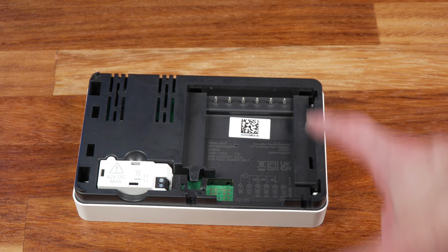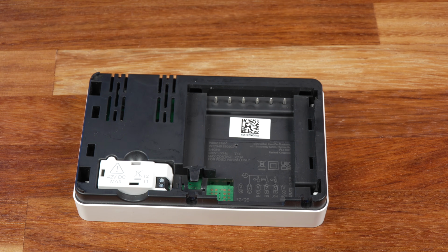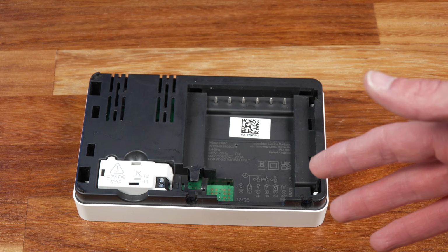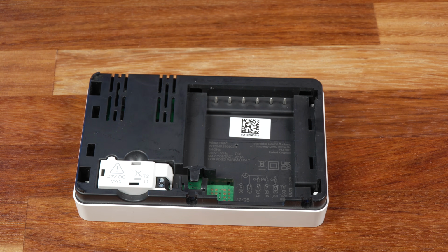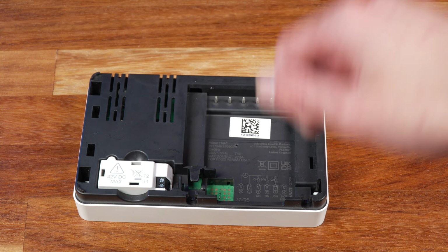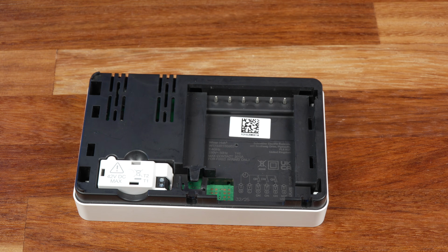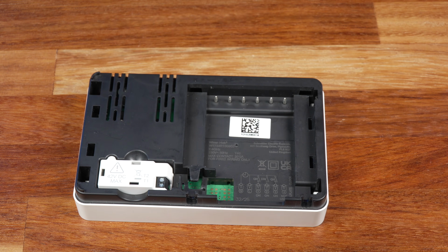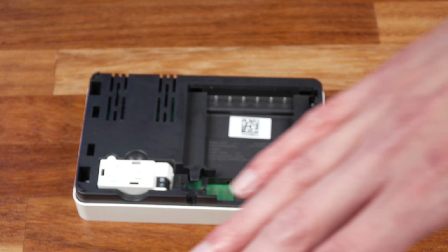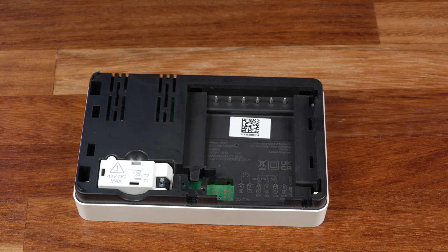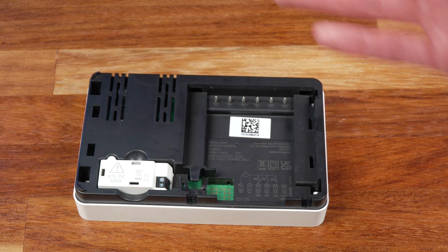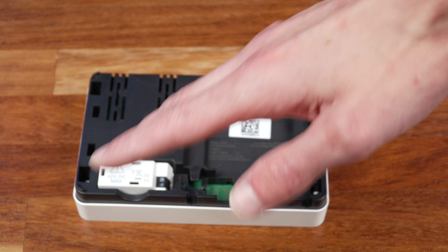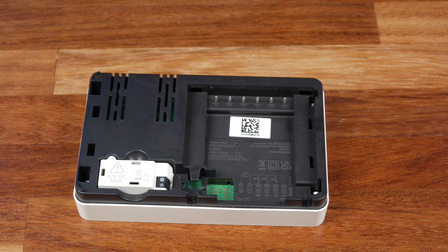With the wiring we looked at previously that uses the main backplate, all that allows the Wiser hub to do is turn your boiler on or off. And when your boiler turns on, it'll run the water through your radiators at whatever temperature is set on the front of the boiler, which isn't ideal, because if the temperature set on the front of your boiler is too high, what can end up happening is if the rooms are not needing that much heat, the water can come through the radiators, get the radiators far too hot, and then you end up with a situation that the rooms heat up too much, heat beyond the temperature set point, and then by the time the thermostat realises and turns the boiler off, the room is still heating up and getting a bit too hot. And you might have noticed this yourself.